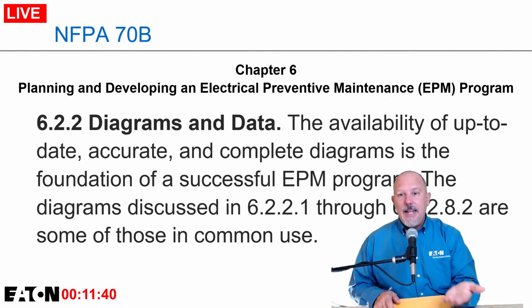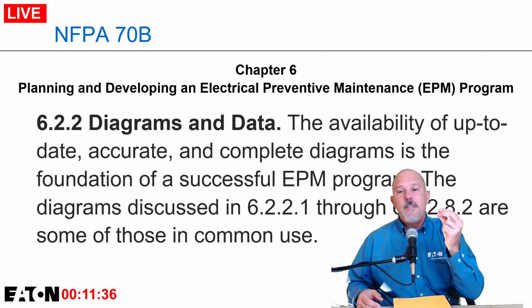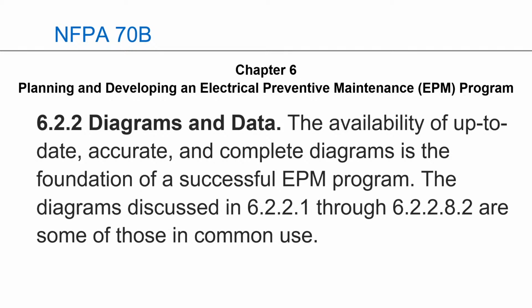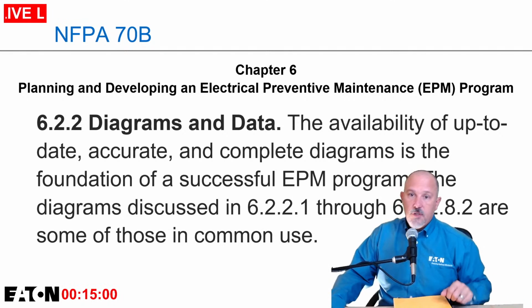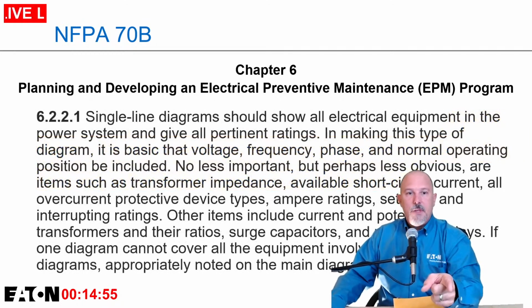6.2.2, diagrams and data. The availability of up-to-date, accurate, and complete diagrams is the foundation of a successful EPM program. The diagrams discussed in 6.2.2.1 through 6.2.2.8.2 are some of those in common use. So the one-line diagram is critical. It has to be updated.